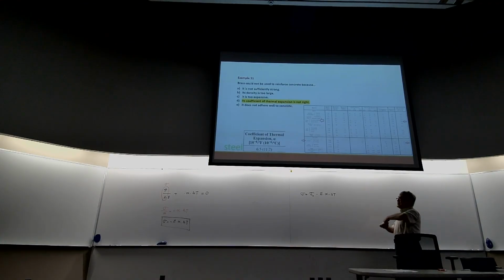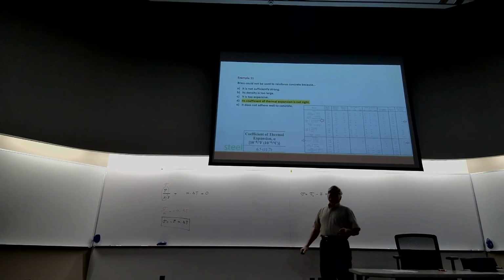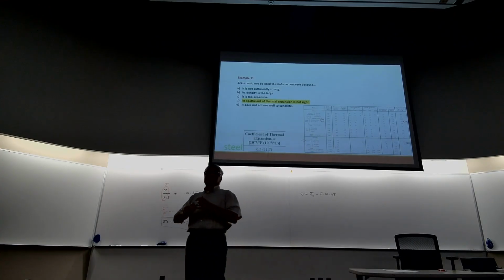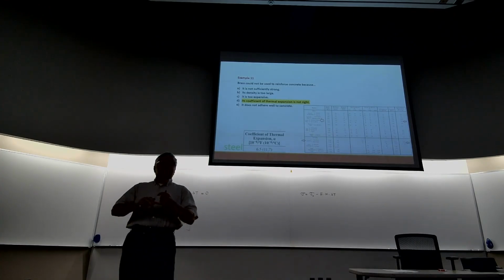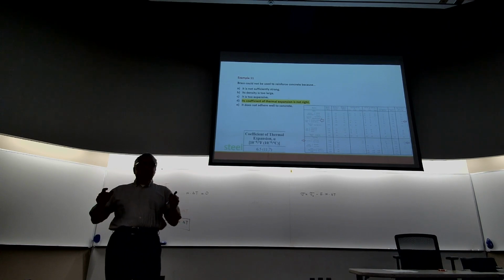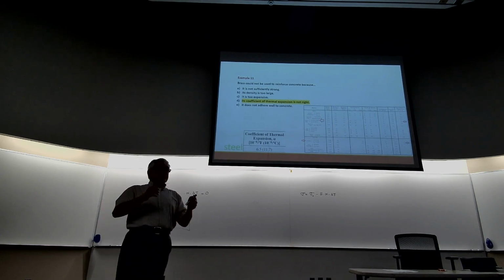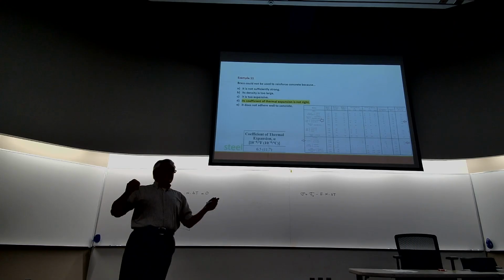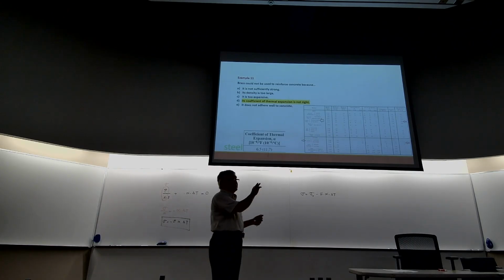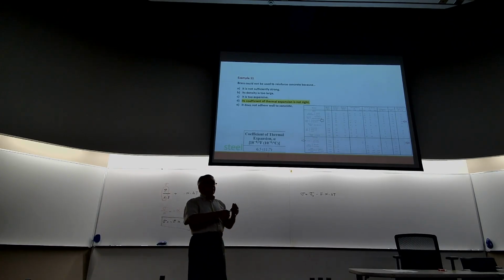So what do you think will happen if the alphas are very different? Brass versus concrete. If you reinforce concrete with brass and the temperature changes, because the alphas are very different, the materials stretch by different amounts. So they are going to separate. Questions about this example?